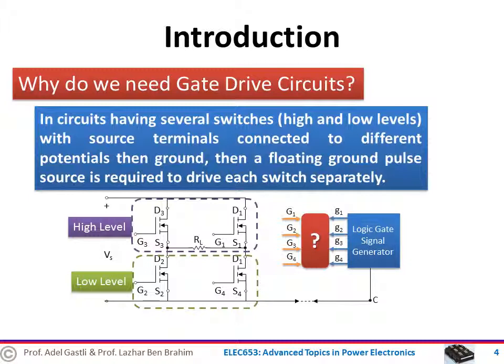So in this case, we need to isolate the gate drive circuit from the power circuit in order to achieve a floating voltage between the gates and the source, which is not using a common ground as the logic gate signal generators and the power converters.